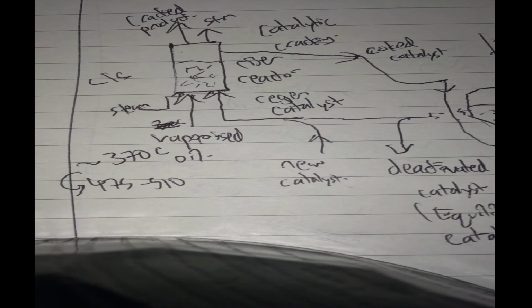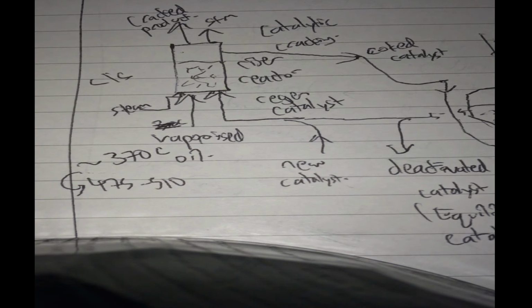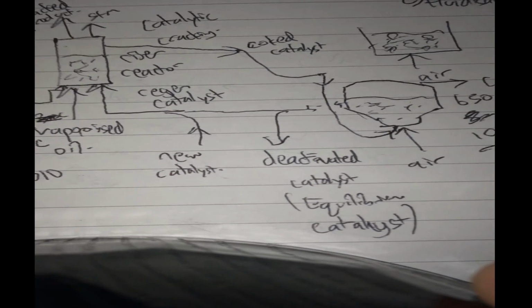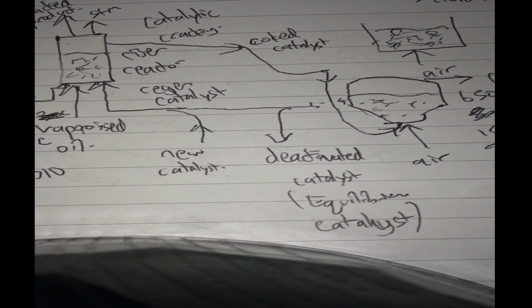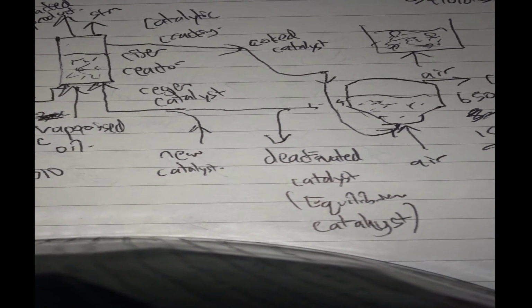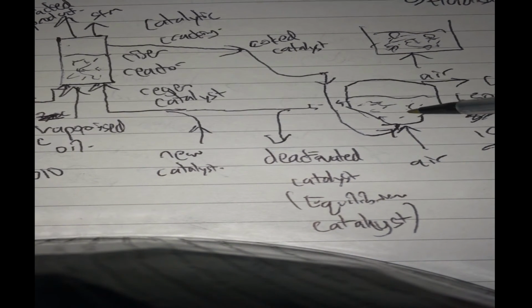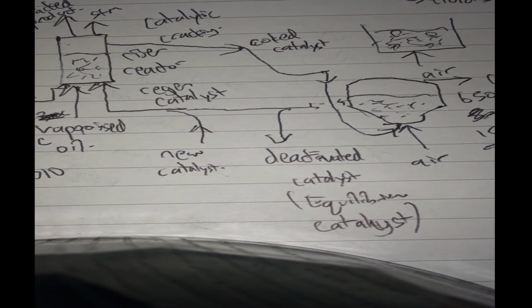And with more catalytic cracking, you are going to have more product. But if I cycle too much of my catalyst and we don't have enough coke generation, then there's not enough heat to be produced in the regenerator. So that has to be controlled to maximize the yield.